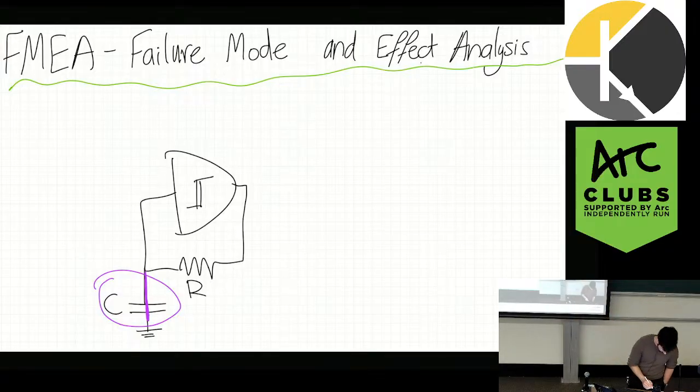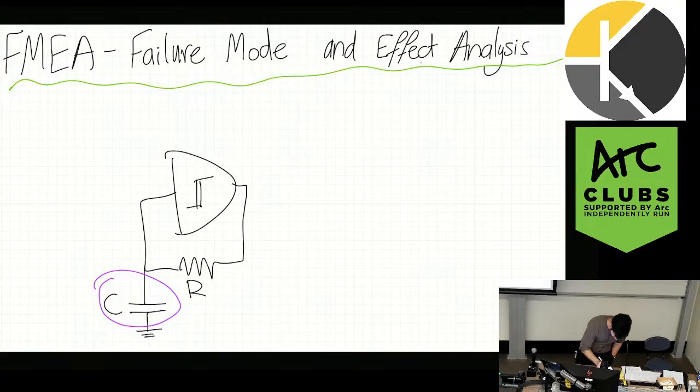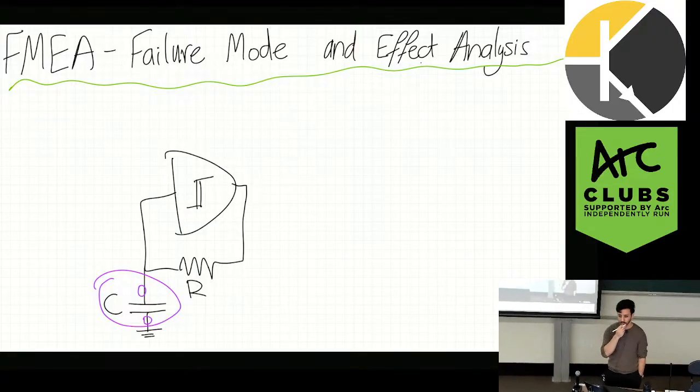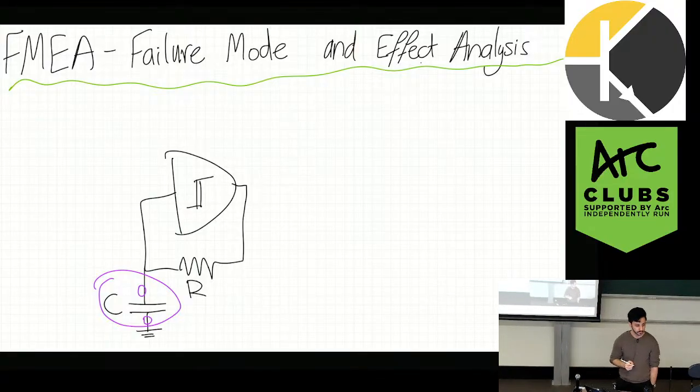And then you could also conversely look at what happens if it's open. If something goes wrong and it opens, what would happen? It depends on the output purely. Depends on the output? In what sense? There's not going to be any current going through the resistor, so voltage levels input equals output, right? Yeah. That's true. Input equals output. That depends on how the Schmitt trigger is built. Most likely it's going to oscillate at a frequency dependent on the propagation delay of the Schmitt trigger. You're both correct.